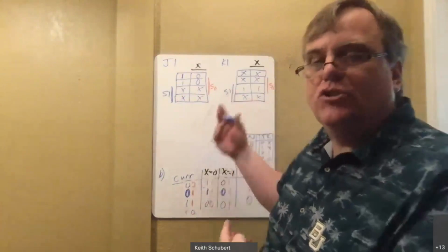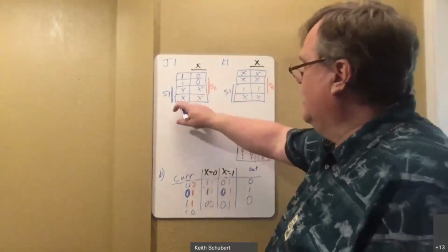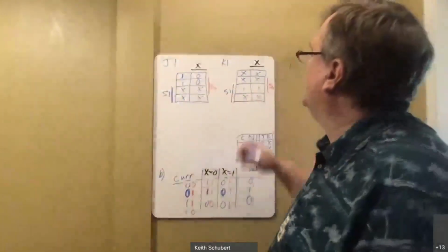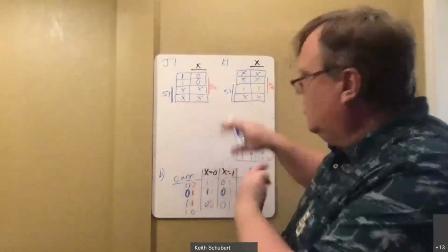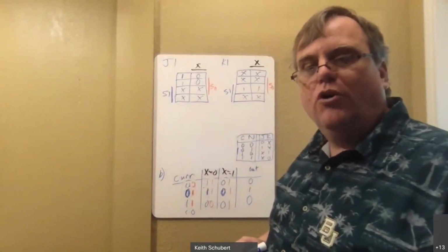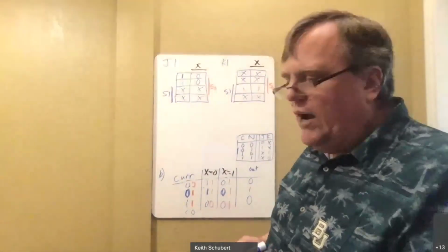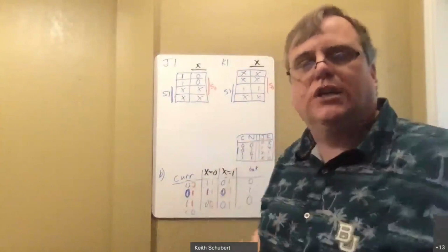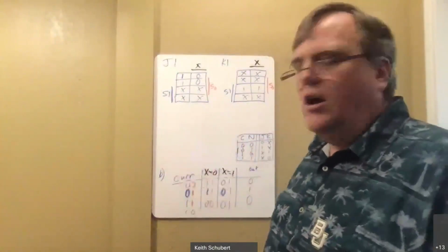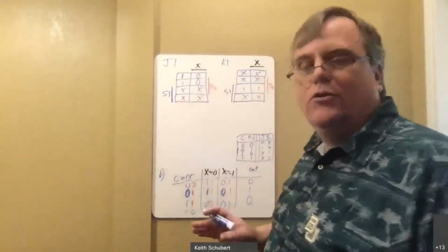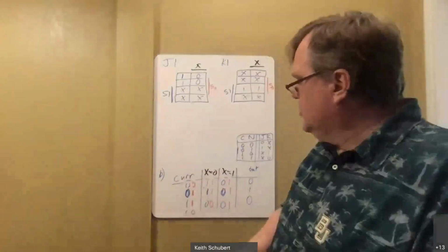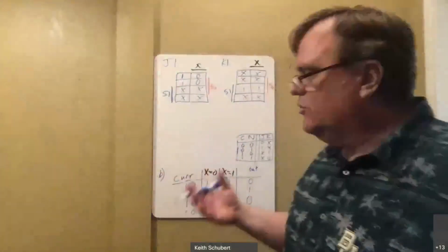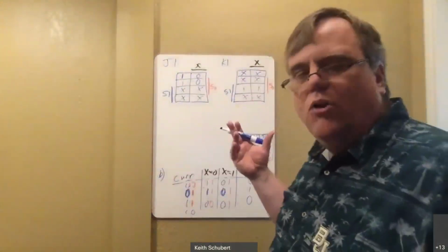However, I can't say it's wrong because I didn't tell you what to do. Therefore, on a test, this makes your life easier. If I'm on a test, I would just say, hey, that last line, you didn't specify. On a test, this is much quicker and easier to design. So I'm going to pick don't care for all those states to make my life easy. If you write that statement to me, and I hadn't told you what to do, so the assumption is correct, which it is here, then I'd be like, awesome, good choice. You could also justify whatever pattern you wanted on it. If you picked a reasonable one, I want it to go to 0 every time or whatever, I'd be okay with that too. You could just say 0 is my reset state or something. That'd be a fair way to go also.